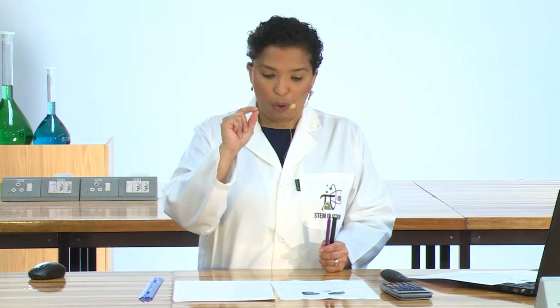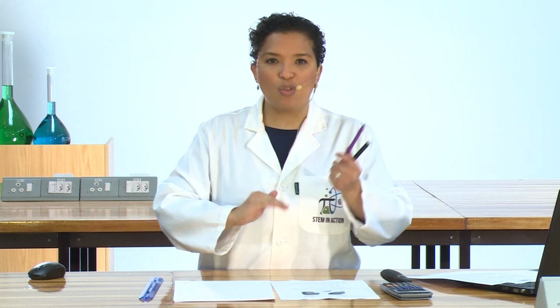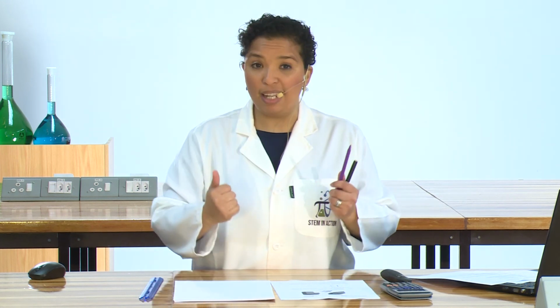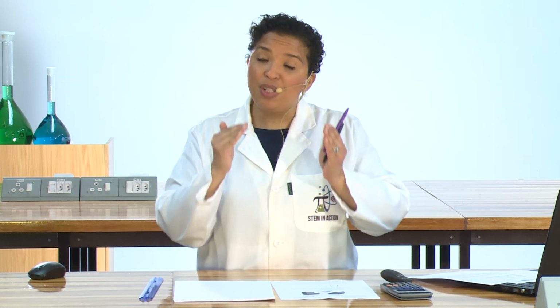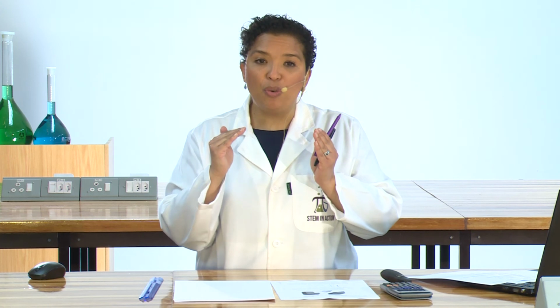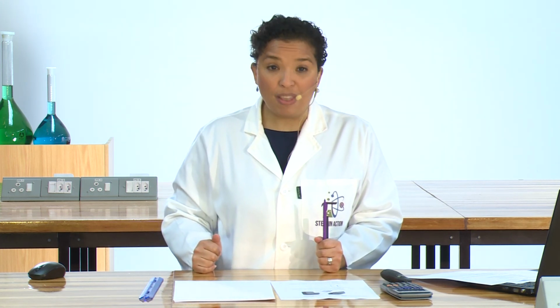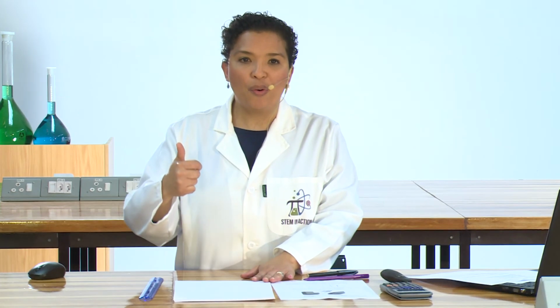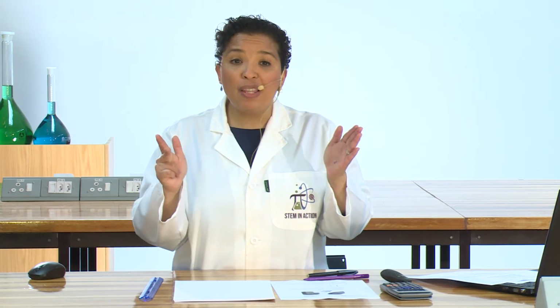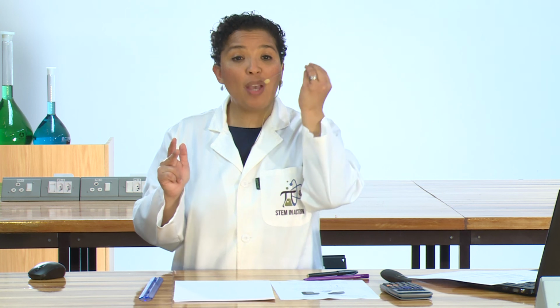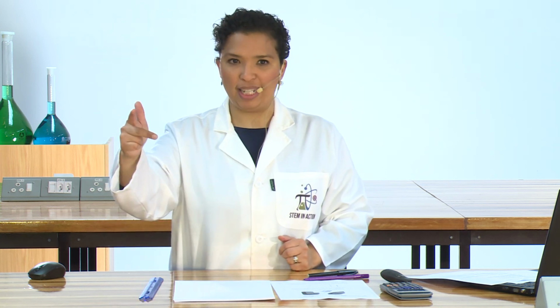But we need to describe it either from X to Y or Y to X. So your answer can't say clockwise or anti-clockwise or from positive to negative, anything like that. They tell you which notation you need to employ to describe the direction of the induced EMF. So we know that we need to determine the direction of the induced EMF, and because we have a generator, we're going to use Fleming's right-hand rule.